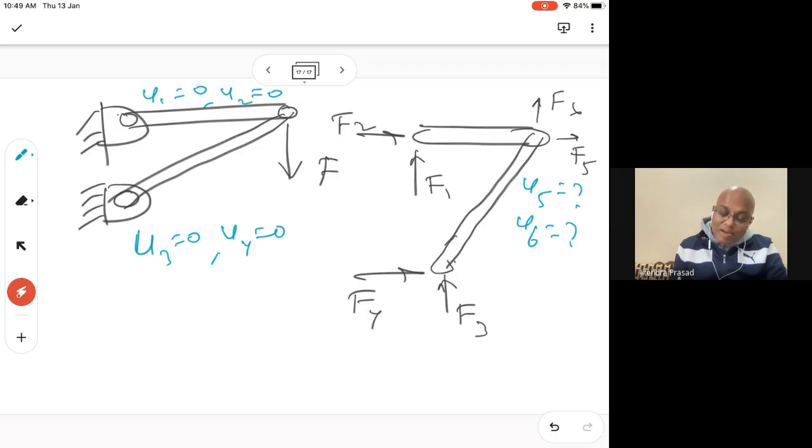Now you see, earlier one node had only 1 degree of freedom. Now one node has 2 degrees of freedom, because this is how the displacement is defined. The displacement is not the absolute one, and we are not interested in that. We have to find out in X direction what is the displacement, in Y direction what is the displacement, and it makes sense because all the directions are independent, meaning that the sum of forces in X direction is equal to 0, for example.